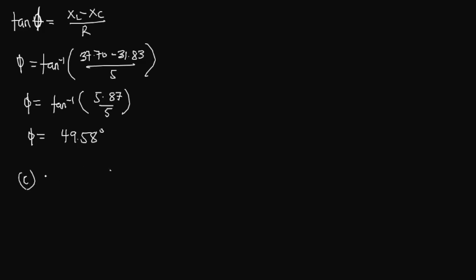To find our voltage, we know that voltage is equal to current multiplied by the impedance, but this time around it is the impedance of the coil. Now the impedance of the coil is equal to, when you have an inductor and a resistor in series, the square root of R squared plus XL squared. So this is the formula that we use to find the impedance of the coil.